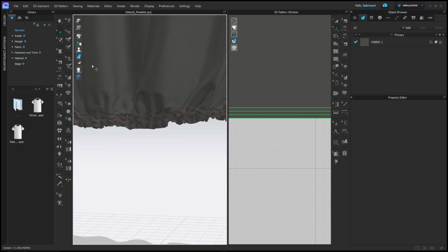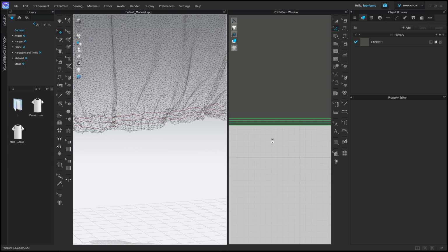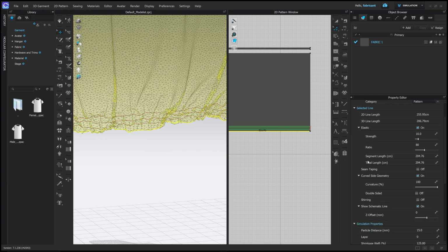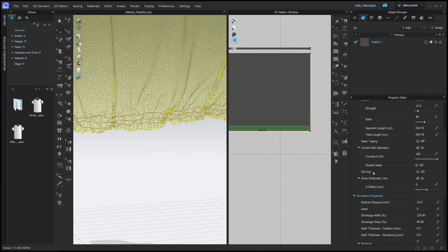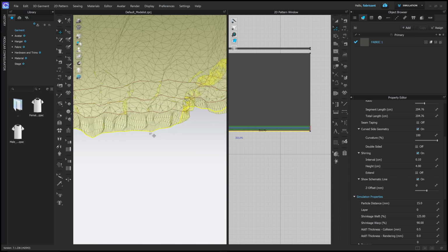The thing that you will notice if we look at this mesh in the mesh view, so I'm selecting on the left side to go to mesh view, is that it gets a bit screwed up, and we can combat that. If I click one edge, just the edge of the pattern, and I go down to the right side to the shearing option and put the checkbox for shearing on, you'll see now that from here to 4 centimeters, we have a lot more mesh to give us definition of how this is going to fall together.